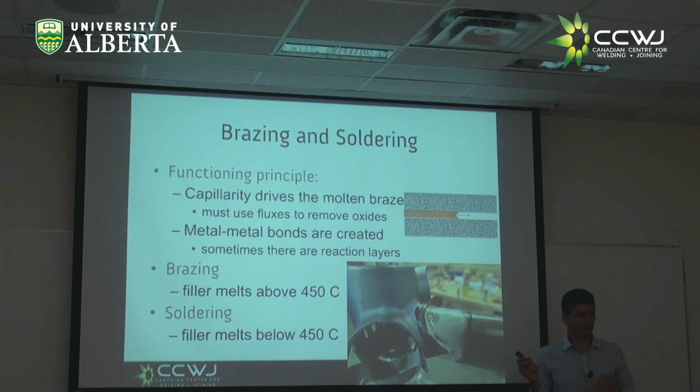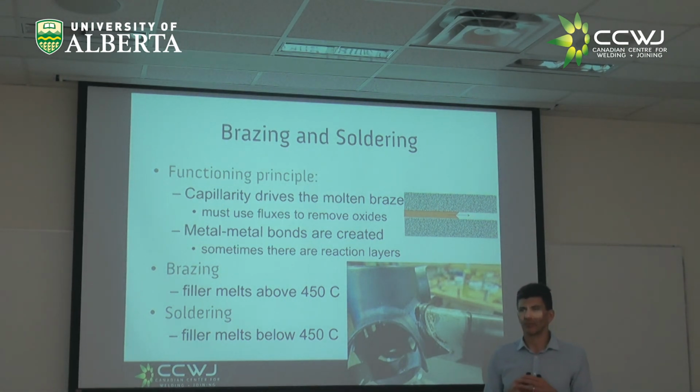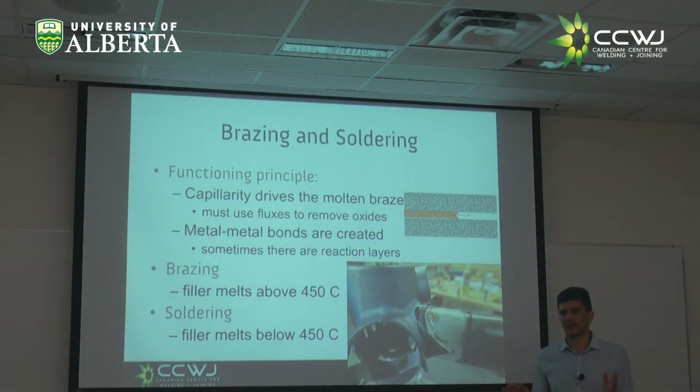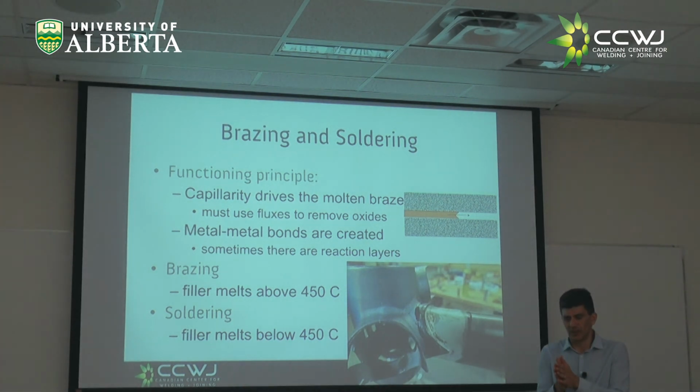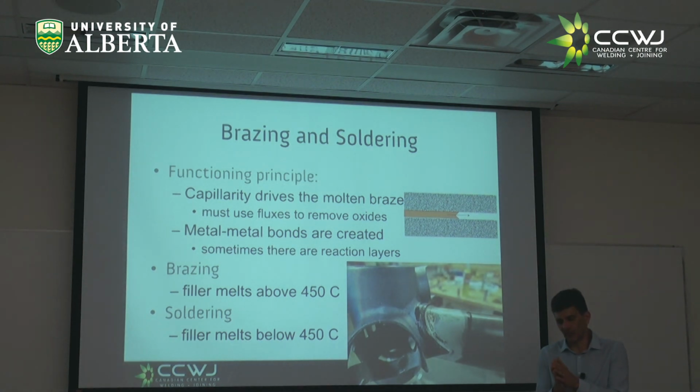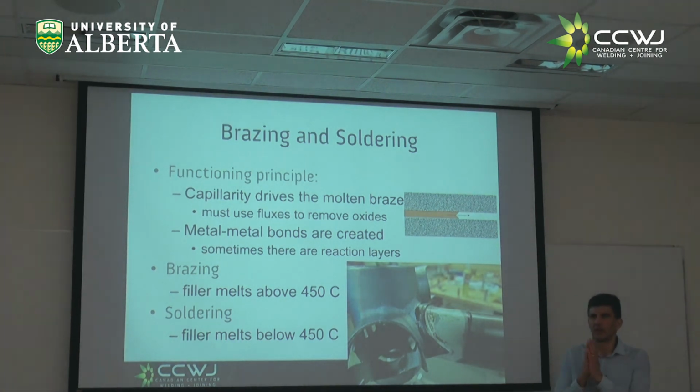Any questions regarding brazing? Okay. Yes. Does it have to be a flat configuration for brazing and soldering? Excellent question. Doesn't have to be, but I've never seen that it's anything else. And the main reason is two flat things or with low curvature are easy to put together, pretty much in touch. If you have a more sophisticated curvature, it can be difficult. But I am certain that there have to be applications in which things are not flat. In soldering, it's not flat at all. When you're soldering your circuitry, right? It's different.